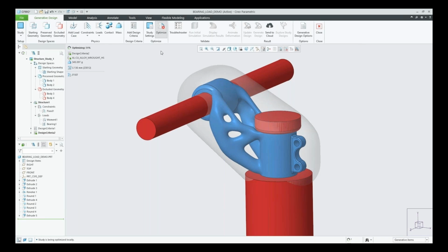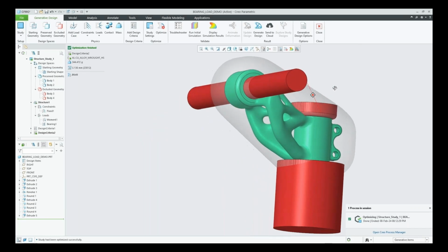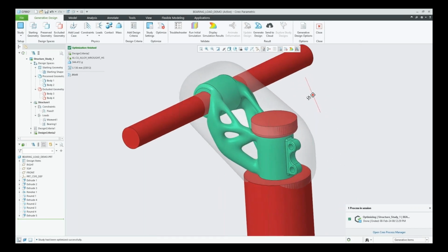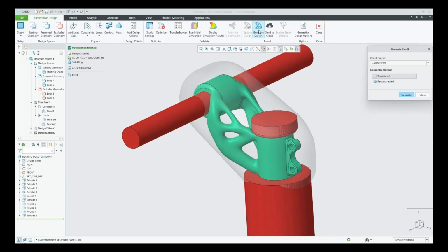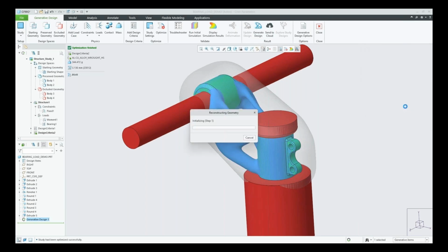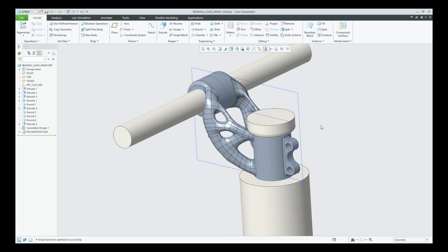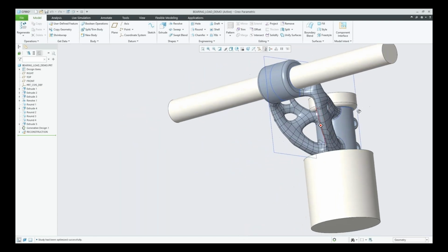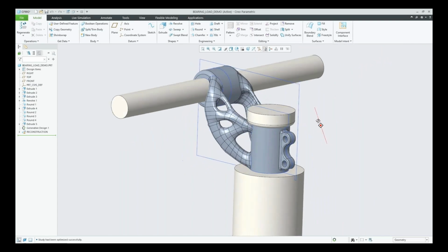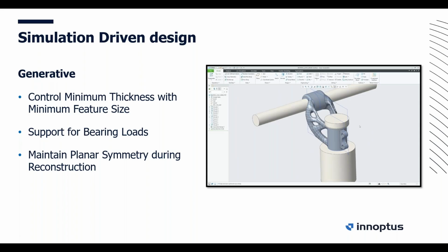So it creates a shape. This is now still created as a tessellated part. Typically, tessellated parts are very hard to change, but in Creo we have the functionality to change that part to a freestyle model as close as possible, which also pushes the symmetry functionality in, and on the freestyle model I can still change my part or remove things or change the geometry if I want.